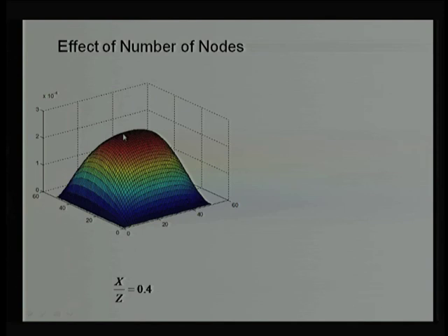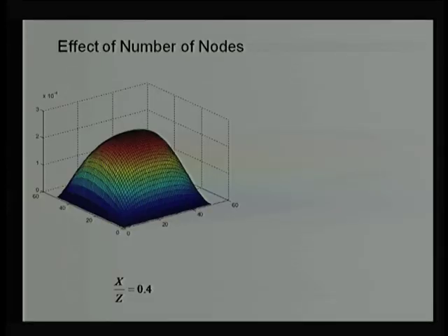This is a straight linear problem, and increasing the number of nodes is not going to vary the results much. It is not a nonlinear problem. The film thickness is also a linear variation, and that is why we do not get a significant improvement with increasing the number of nodes. But we should always try, and if we are getting better results, we should emphasize that.